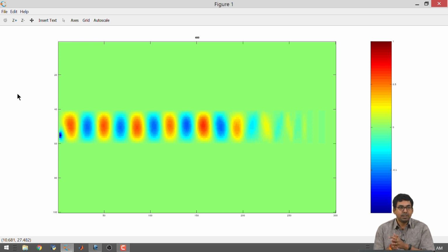maybe the number of modes that can be supported by the waveguide is higher, okay. And if the number of modes supported by the waveguide is higher and if your operating frequency is above the cutoff for more than one mode, then you may be able to excite more than one mode, alright. That is why you are getting some very different patterns when you move the source from top to bottom of the waveguide, make it asymmetric, etc. But if your plates are going to be closer to each other, the number of modes that you can excite for a given operating frequency is lesser, maybe it is just one in this case, right.